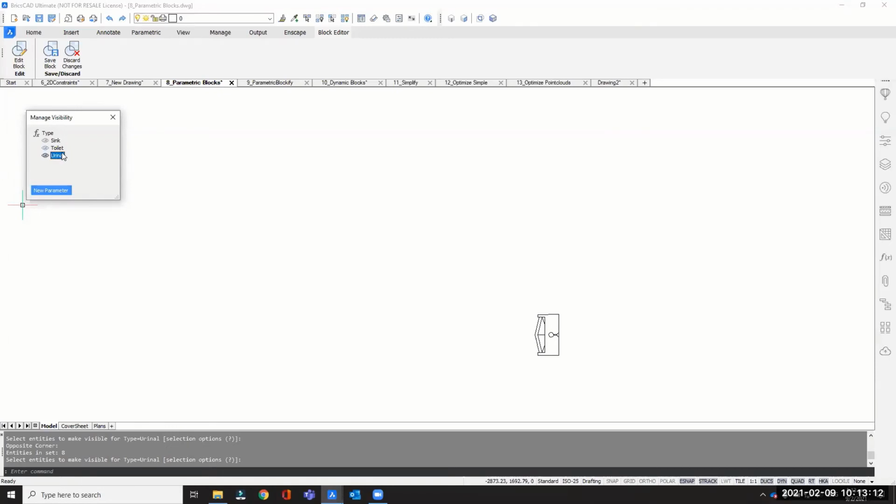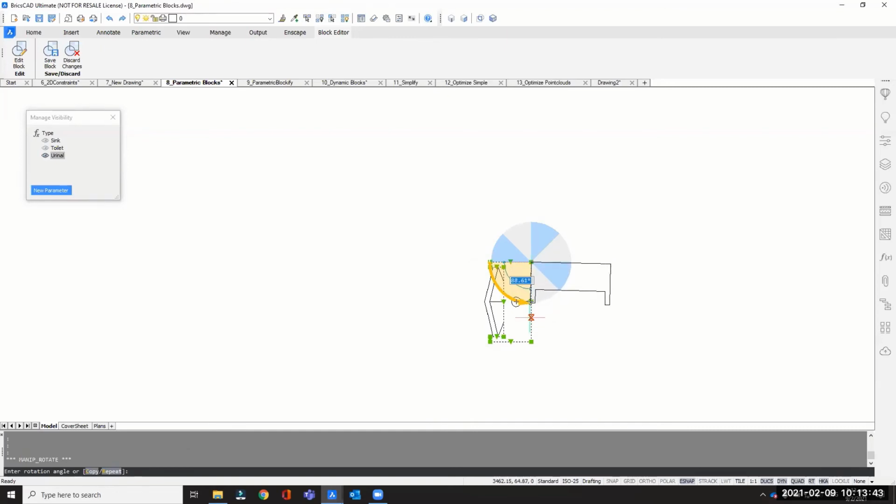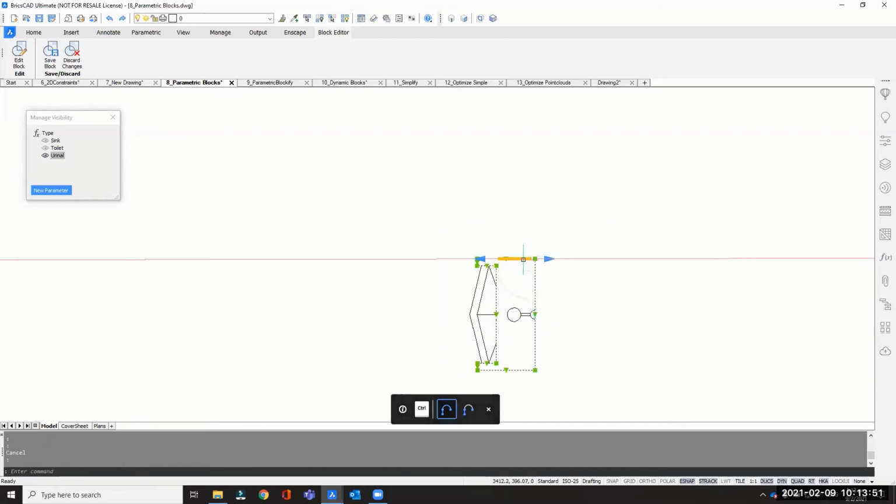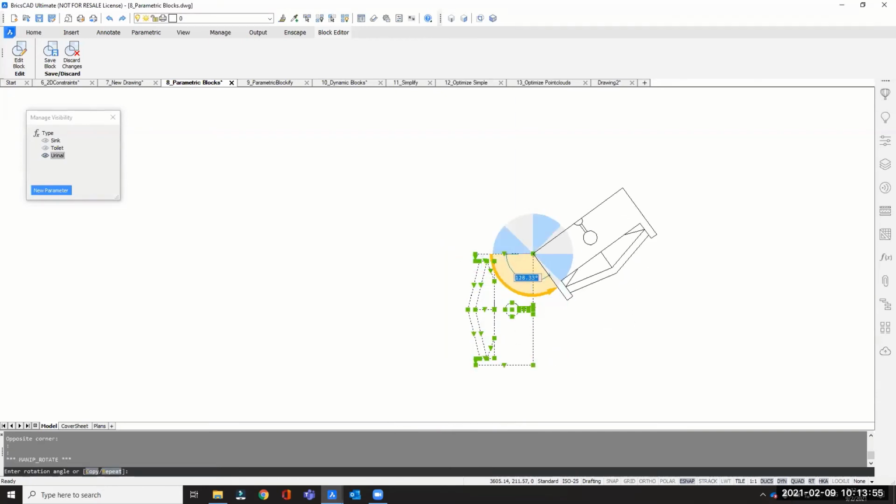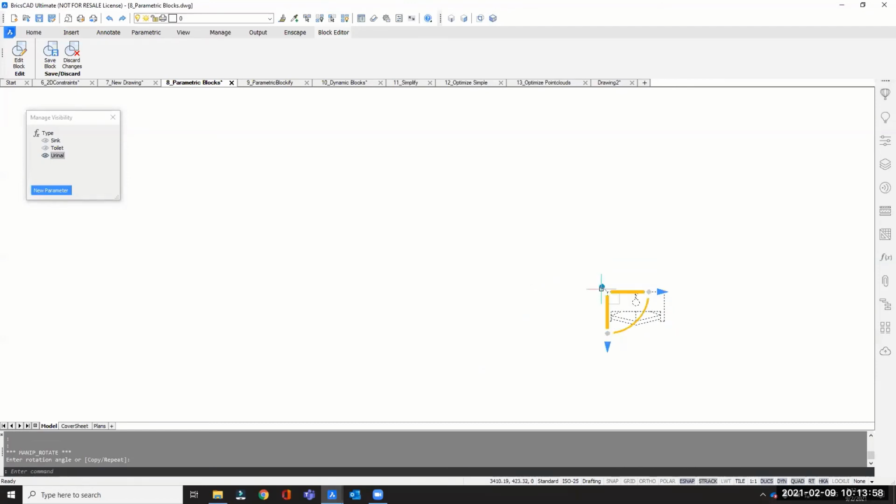So now I see that these are not yet the same orientation with each other. So I just want to reorient these three so that they're all in the same position when I select the entities and the option that I want. So I want to just rotate this using, again, the manipulator. Maybe rotate it this way. Oops, sorry, select everything first and rotate that 90 degrees, and make sure that I move this to 0, 0, 0.